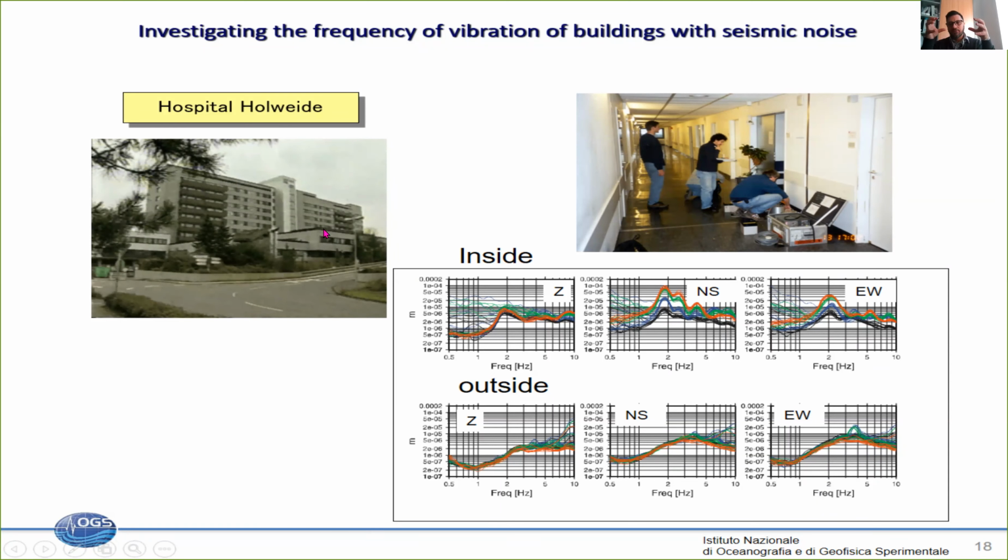an hospital that is made mainly of 3 blocks, let's say in this way. And also the engineers, they were making with us measurements here, they didn't know exactly from the design if a building was behaving like a unique block shaking altogether. I think Chiara knows this problem quite well on what I'm talking about. Or like 3 separated completed blocks, or like 3 blocks linked, let's say, like by springs. So we made measurements in the hospital inside and outside. The first thing that you notice is that the colors are representing the measurements made at different floors.